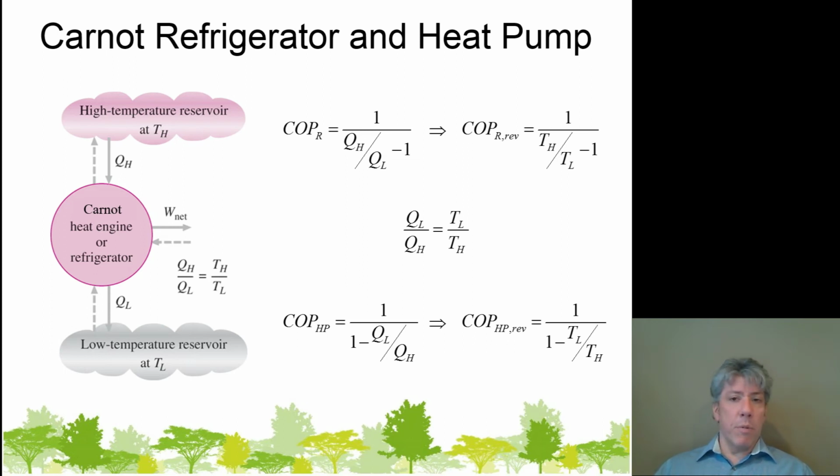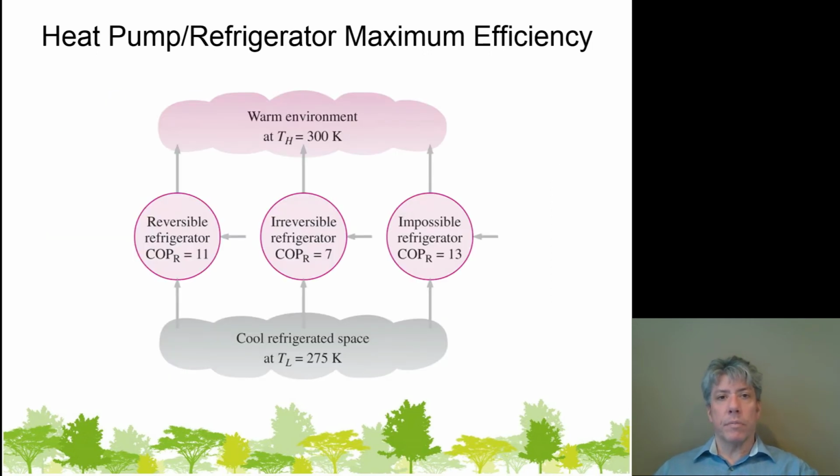And the maximum efficiency it could ever have is governed by that equation right down there. If you know the outdoor temperature, that's TL. You know the indoor temperature you want, that's TH. And those temperatures determine the limit of efficiency. They determine the minimum amount of electricity I'll have to pay for in order to warm up my house. So the maximum efficiency of a heat pump or refrigerator can be calculated.